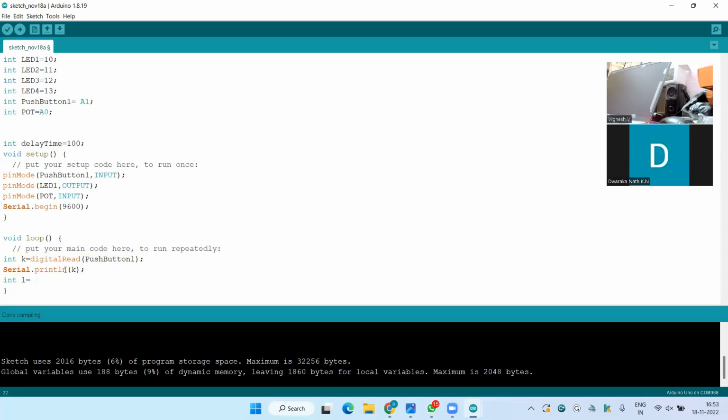Now I'm going to change small things. I will tell you where I'm going to change this. This is my analogRead, and I'm reading the pot value. The pot value is recorded here. Now I'll print the pot value: println l. But I'll make small changes here. Here k is there. I'm removing the ln command, and here I'm going to create some space.